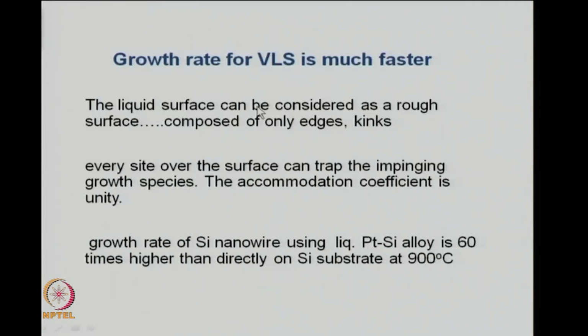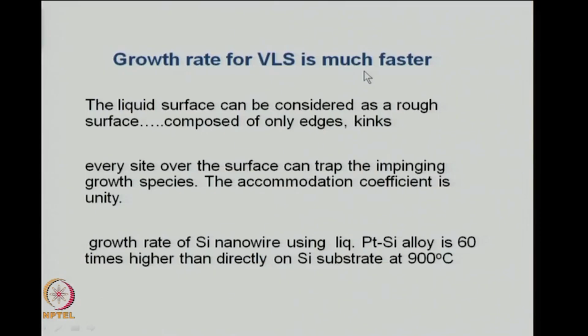Now, one of the things is that if you compare with other growth methodologies, the VLS method is much faster. This is because in this case we are using a liquid droplet as the catalyst, and the liquid droplet, as we discussed earlier, has all the surface for it to accommodate the incoming gaseous particles, because any point on the liquid surface is good for accommodating the gaseous molecules.